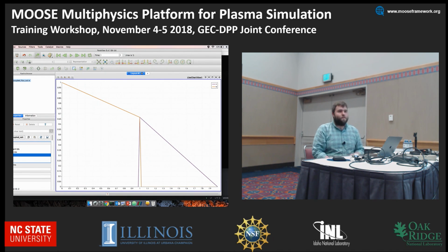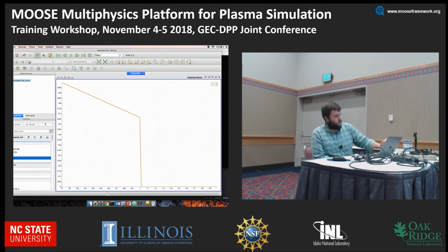Okay, so as we increase the size of the mesh, we see that because there aren't actually any kernels operating on the other side of the boundary, and we'll isolate U, our kernel is active on the left and not active on the right, and so we see an immediate drop in the value of U past that interface.